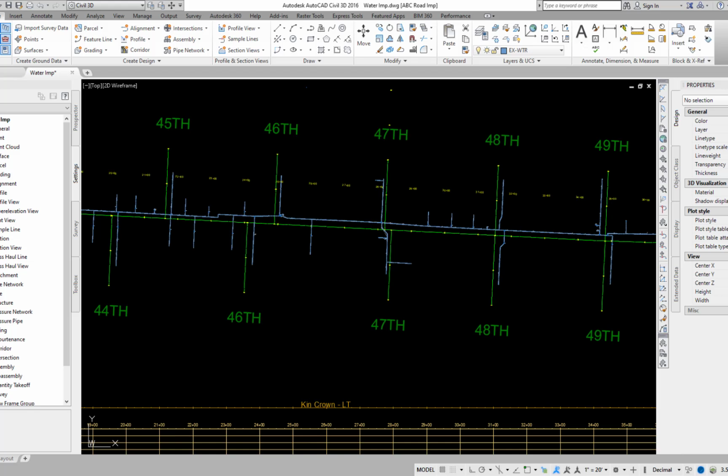To reduce fittings, the water pipe should be deflected at joints where practical and where space is available to obtain the required clearances. It is generally a lot cheaper to deflect pipe than to install bends, especially on larger diameter pipe where bends can be very expensive. Where a bend is installed and there is sufficient space available, 22.5 degree bends are preferred over 45 degree bends. This is to reduce the pull-out force at the bend joints. There is also less pressure drop with a 22.5 degree bend. This, however, is generally a very minor concern in a normal water distribution system.